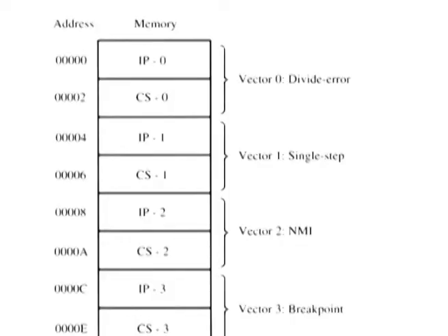The pointers 0, 1, 3, 4 are required for 8088's internal interrupts. The pointer 2 corresponding to the second entry in the interrupt vector table is used to identify the starting location of the non-maskable interrupt service routine. The pointer 0 is for divide by 0 error, which indicates that program control will be transferred to the address pointer 0 on the occurrence of divide by 0 event. The pointer 1 is for single step mode, which indicates that the microprocessor is set in a single step mode.